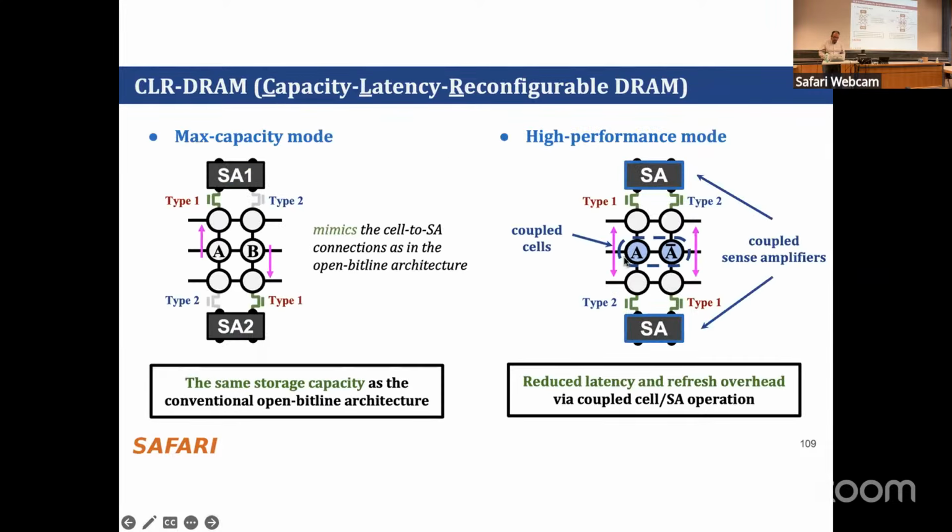Yeah, so essentially when you want to read, you need to activate this cell, and that would affect your bitline per chip. But this cell also, if you make it a negative one, and given this open bitline architecture, where one bitline is for the negated data and another is for the original data, these two can work together to increase the current for you, and that can cause a much faster activation time.